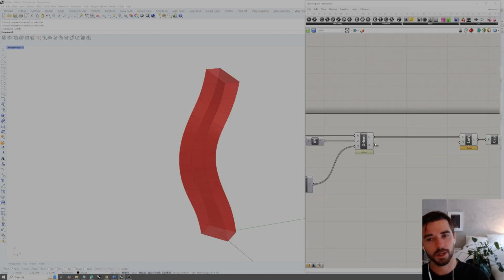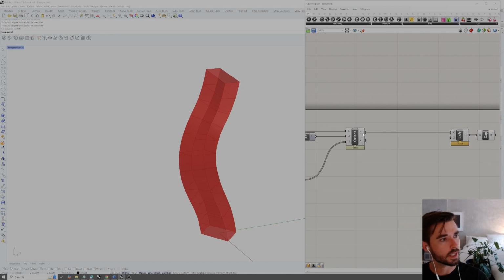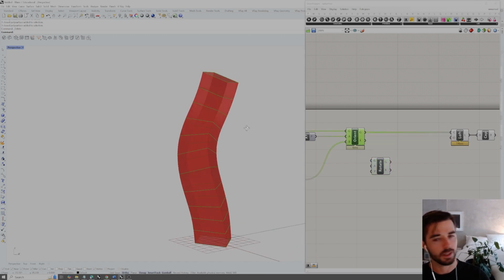So if we wanted to rotate this first, we can double click and type rotate and preview the component for the rotate command inside of Grasshopper. So this rotates an object in a given plane. Well, the object we want to rotate are going to be these sections that we've already placed on our curve. So we know that that's the geometry we want to rotate.